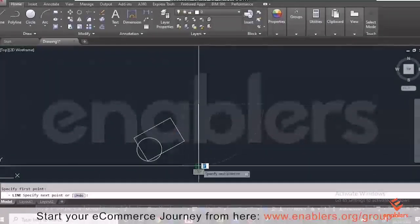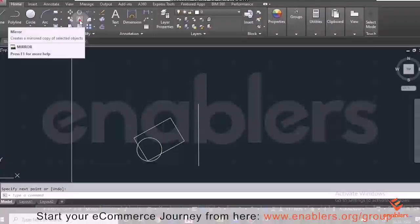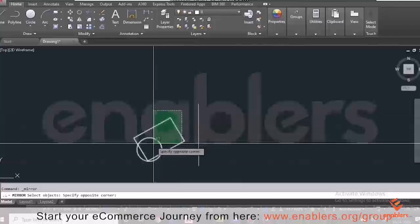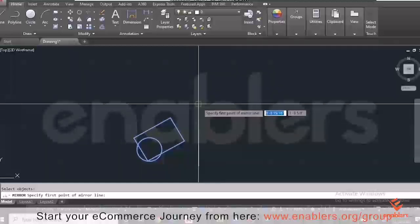Alright, and I will talk about the mirror tool, which is right here. Using the mirror tool, you can make a mirror image of any object. In this case, I will select this rectangle and this circle. I will press enter, and now you need to specify a mirroring line.